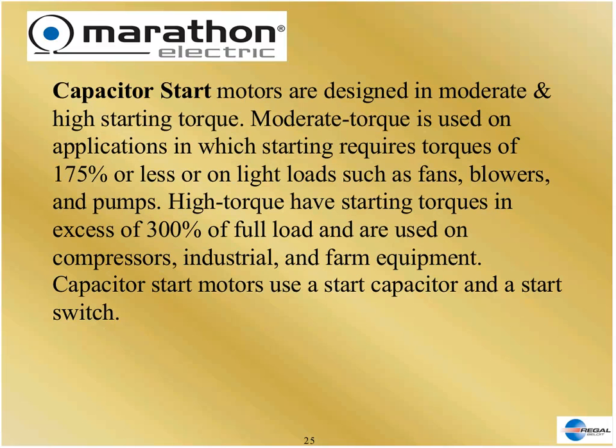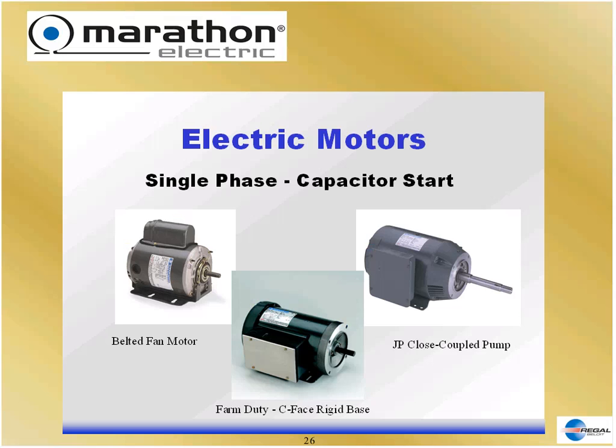Okay, so what if we have a constant torque load? What if we don't have a variable torque load, and we need a lot of starting torque, and I can't get it out of the split-phase motor? Well, this other single-phase motor we designed, which is more of a general-purpose motor, is a capacitor start motor. Capacitor starts utilize a capacitor to give the motor more torque at starting.